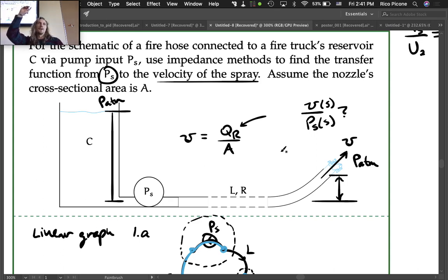Each particle in the fluid has a different potential velocity and pressure associated with it. Whereas for us, everything in the hose along this cross section is at the same velocity, which is just a fiction that is useful. We just say it's the average velocity along that profile. That's what we're solving for.